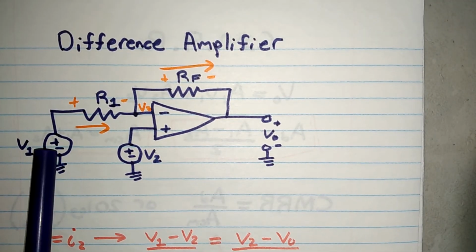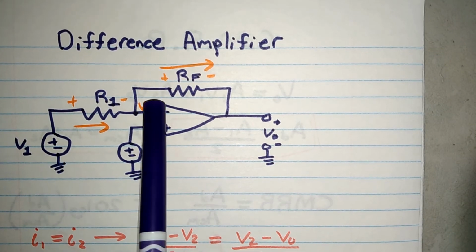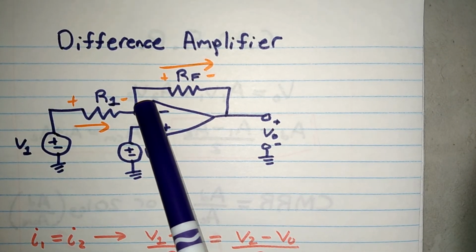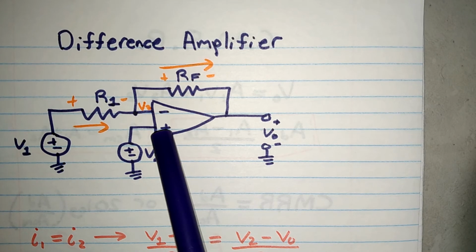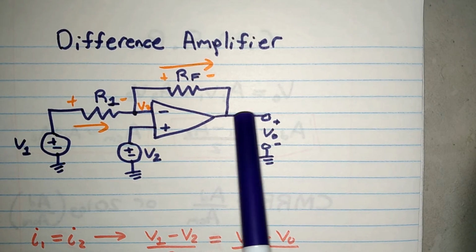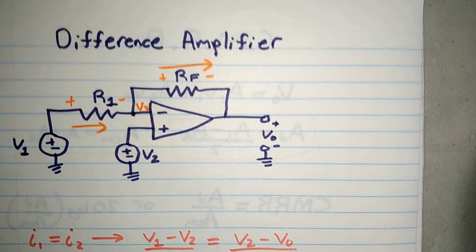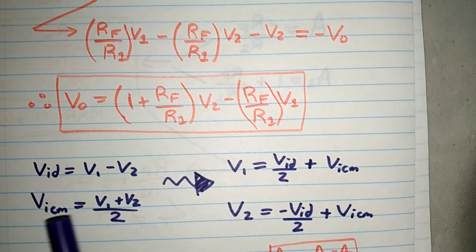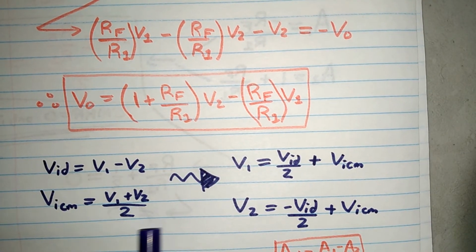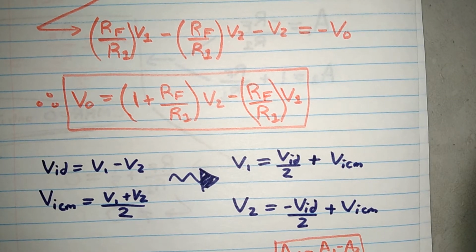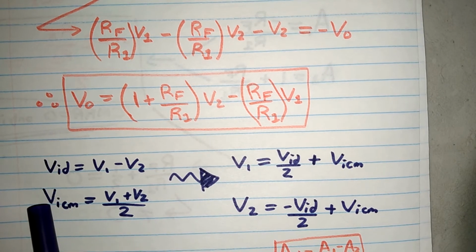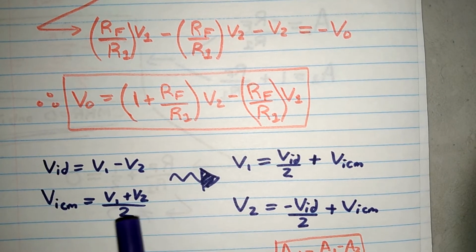But because the input terminal is seeing 10 volts and not 0 volts, it will produce an output. And this is undesirable, not ideal. So what we really want is the common mode voltage gain to be 0. We're always going to have a common mode voltage, but we want the gain of this to be 0.